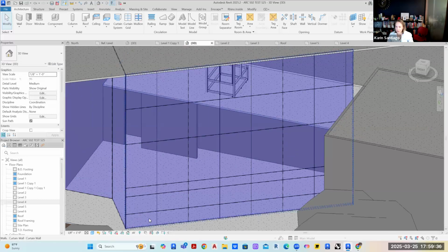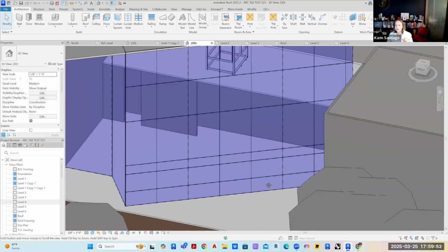And so the mullions help stabilize the glass, they stiffen it, and they also give us a good place to break the glass and then keep adding pieces of glass. It's like a kit of parts of sorts. And in a curtain wall application, we can continue to add glass and we can butt the glass together without a frame, or we can choose to have the frame in many places. Sometimes there's a choice that you can have, and that depends on which one of your directions is supporting.